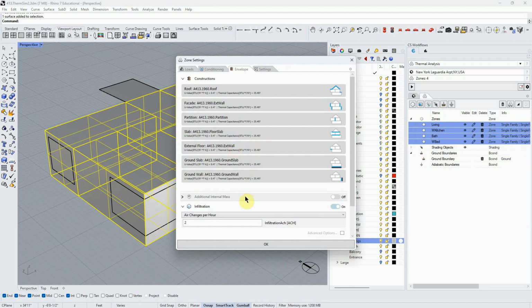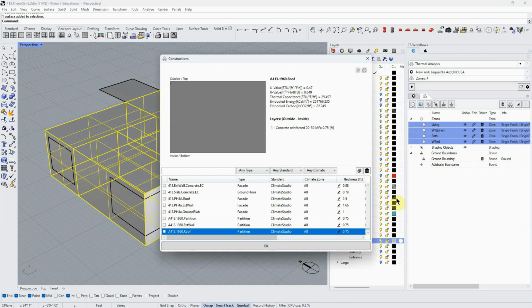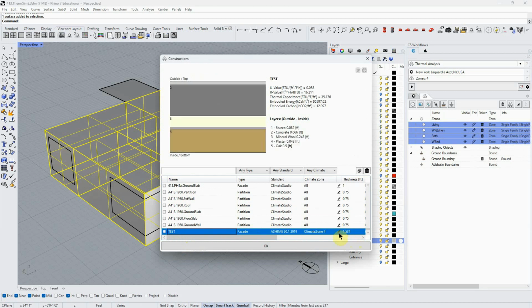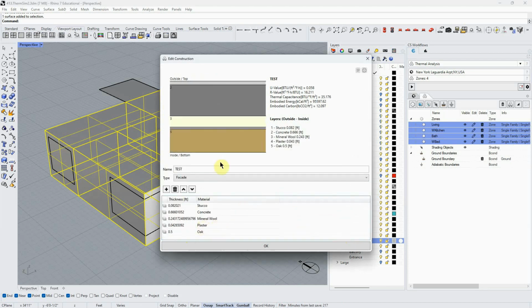One thing I realized is I went too quickly before when I was showing you that test. So let me go back to the tests that I showed as an example. Is it clear what's going on here? In this envelope, here's the outside, here's the inside, and we just have a series of layers. This is a horizontal section through the envelope. Out here we have stucco, and it's 0.082 feet thick.